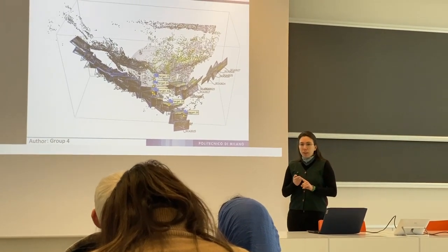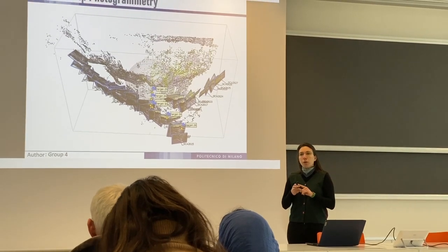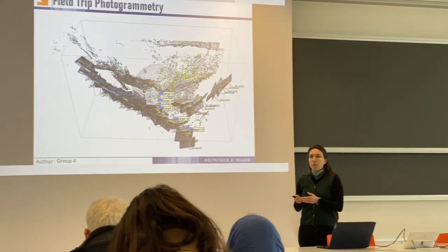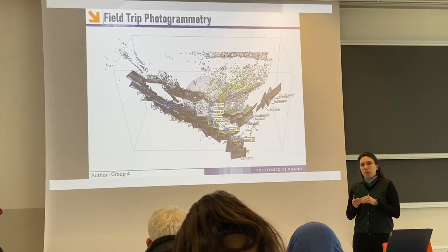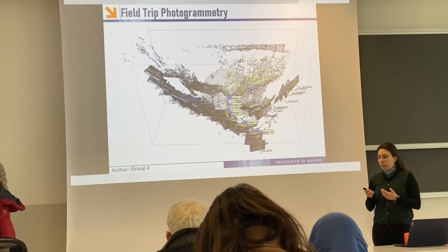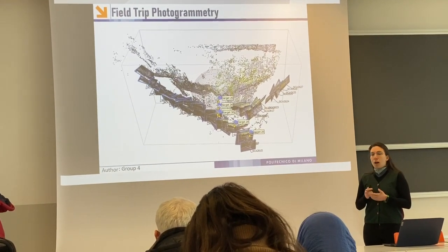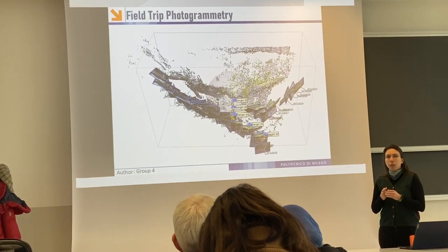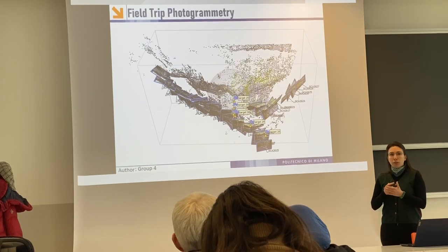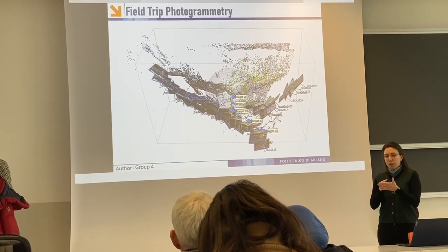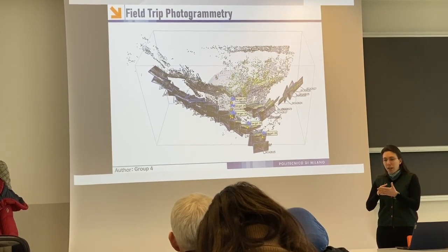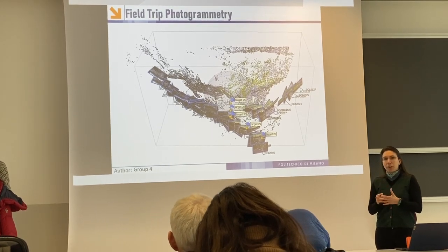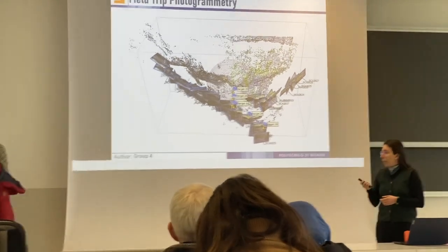Another most important thing, our point cloud should be oriented with respect to north. However, we didn't have geo-reference data. For this reason, we created our coordinates by ourselves. We had horizontal and vertical bars. Based on our coordinates, we started our target from the 0, 0, 0 point, and then based on the difference between the targets, we revised the coordinates.